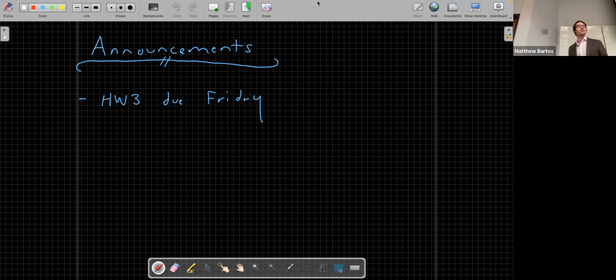Yes. Also, same line of terminology, the drainage network is like the rivers and stuff, the streams that you set up, and then the catchment basin is like the whole watershed. Yeah, so the terminology is kind of fluid. When I say drainage network, what I mean is the network at which channelized flow occurs. So the drainage network in this context refers to areas of channelized flow, areas of piped flow, so anything where there's concentrated flow occurring. Whereas the catchment area refers to the entire land surface that feeds that drainage network.